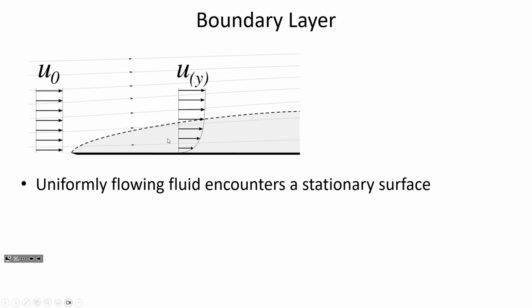And if we introduced a plate, like if we just dropped a metal plate parallel to the direction of flow, then that plate would cause a frictional resistance to the liquid that's in the vicinity of the flow. So here, prior to the fluid encountering that stationary plate, you see that the velocity distribution is even, that as you go up vertically or down vertically, there's no variation in flow.